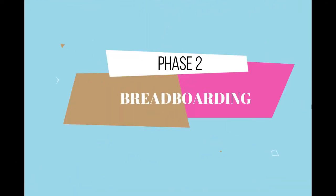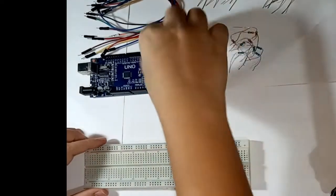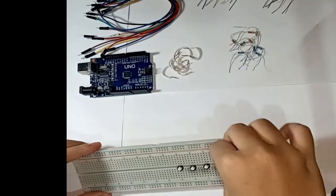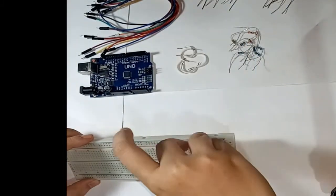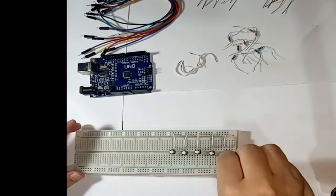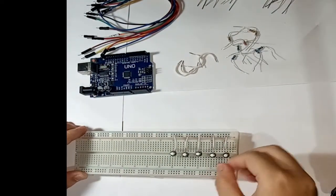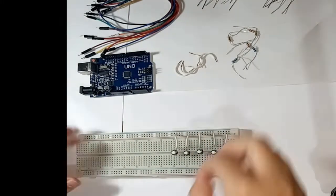I always do breadboarding to test my circuit before permanently soldering it. First, I put my 5 tact switches. Next, I use connecting wires to connect the pin of switches to the positive power rail. I also connect the other pin of switches to the 10 kilo ohms resistor connected to the ground.